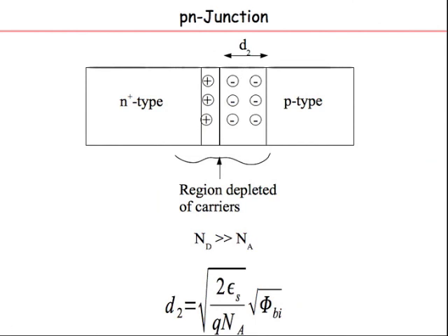So you take an N-type material and a P-type material. What is an N-type material? It's silicon which has N-type dopant atoms like arsenic. So that means there is an excess of electrons. You have a P-type material where you have doped the silicon with boron, an element from the third column of the periodic table. So you have an excess of holes. So when the two come together, there is a junction formed, and this forms a device called a P-N diode.